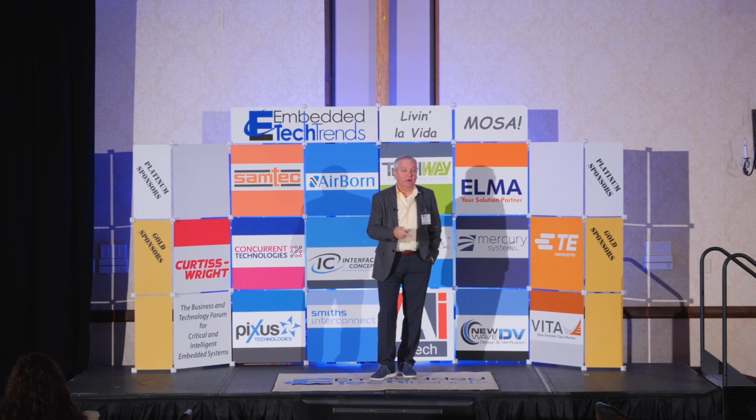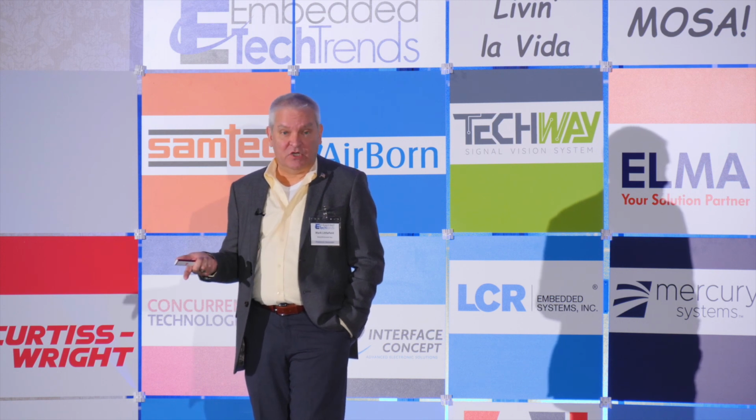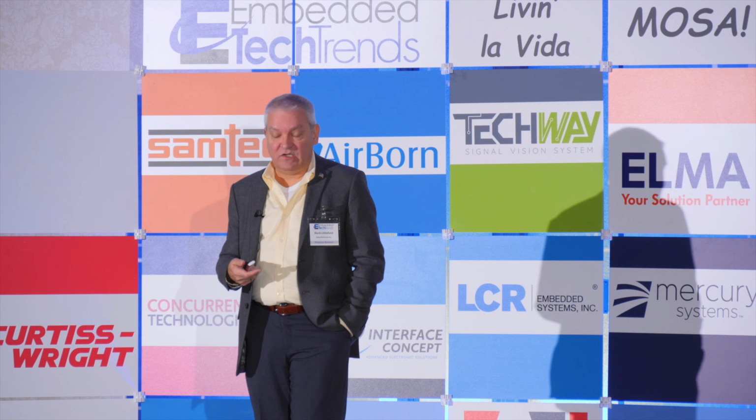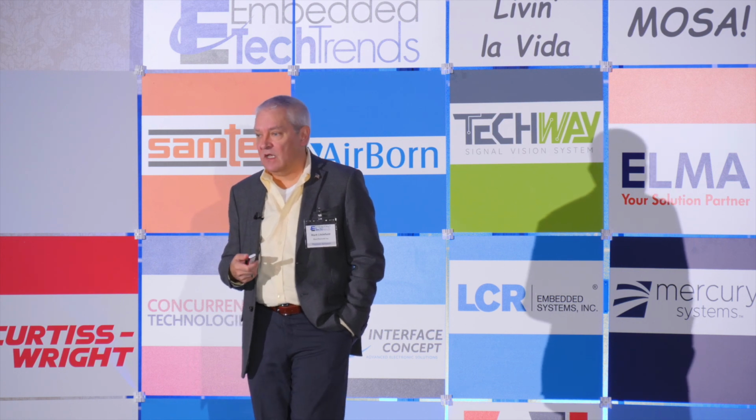For the plug-in card supplier, it is. You can't have a partially aligned card. But you don't have to use the entirety of the SOSA Technical Standard to get the benefits of SOSA, is what I'm trying to say here. SOSA is driving the adoption of VITA 46.11 system management. People are finding that, hey, this is pretty slick, and I can do a lot, making my chassis intelligent. I can do a lot of diagnostics and prognostics. I can better sequence my power up so that I don't have to worry about inrush currents and things like that. There's a lot that it brings to the table, and people are seeing that benefit.